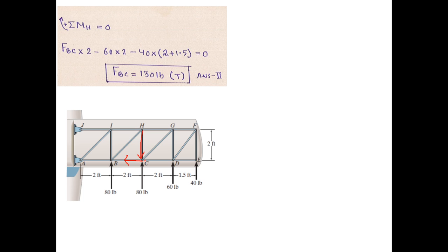So if you want to calculate the rotational sense of the moment of this force, you just have to take this force and join it with the tail of its moment arm like this, and this you will do in your minds. Okay, it's an imaginary step, and then you will use a curl from this moment arm vector R to this force FBC. This is FBC, this is the force.